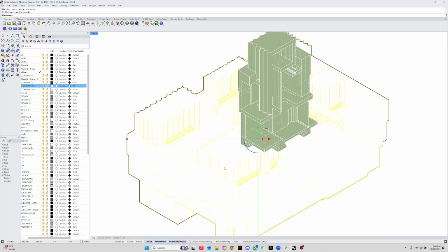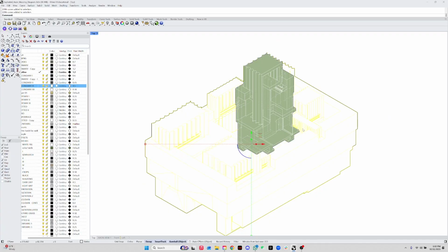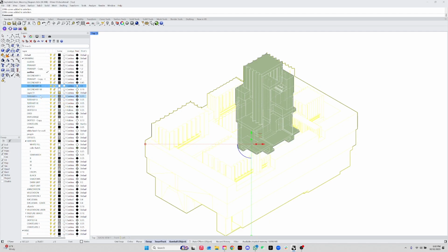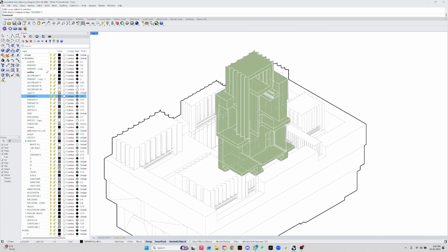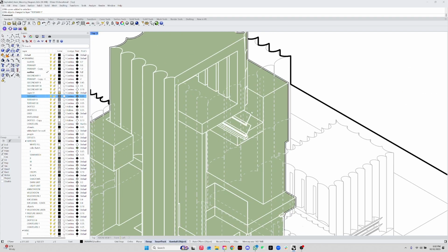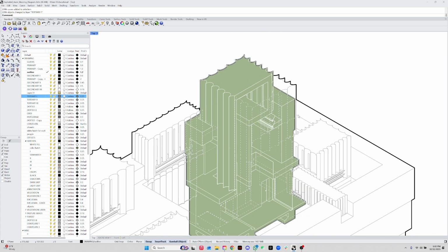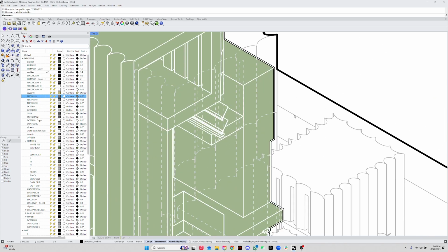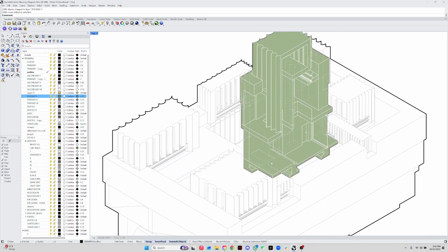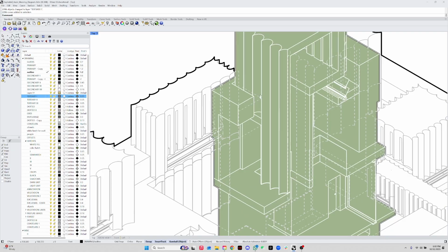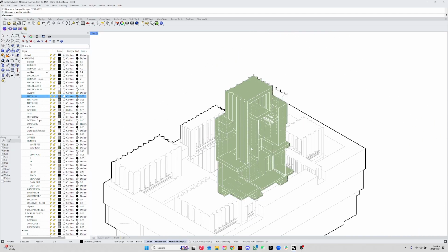Now obviously the next step is to put this in one line weight. I suggest just putting this in only one. If you're using my template, I have 3 line weights in here. I would recommend using tertiary 1 maybe. That one's thin, it's not too thick, and it looks appropriate. Now once you do that, and you have your line weights for your house for the remainder of the project, and then you have your inside lines, and then you have your chunk already in there.